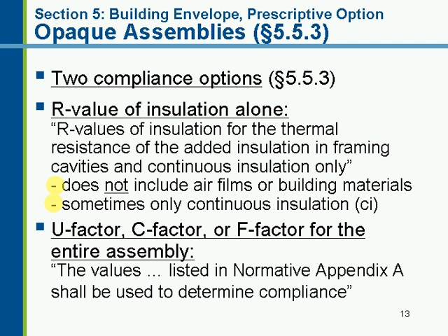Again, if you have some sort of innovative assembly or a different way to approach the situation, you can comply with an overall assembly U-Factor. And the U-Factors for common assembly types are listed in Normative Appendix A. And I'll give you some table references as we go along here for specific assemblies.